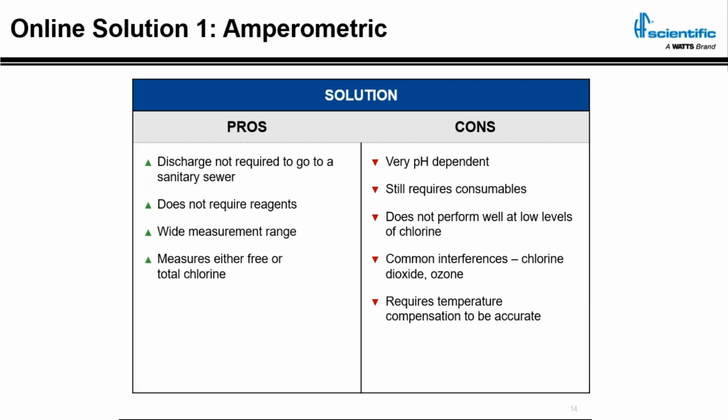If you don't have a high purity pH probe on there, I would encourage you at a minimum to use buffers made for high purity applications, because what we'll see is a lot of drift while it's operating, and then you go in to verify and you put it in a standard, say a 7 or a 10, and it reads perfectly, because pH buffers are very concentrated solutions, and it's very easy for pH probes to read those. But there are high purity buffers that are made for high purity samples that can be used and make that pH measurement more accurate to reduce the error that you're going to have there.